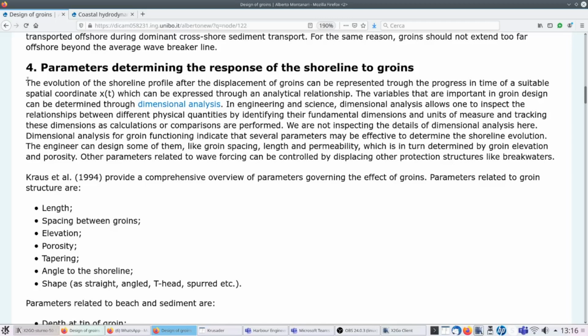Actually, what models it is the difference in along-shore sediment transport as we move along the coastline, where we have a positive difference, meaning that the sediment transport is increasing. It means that there is erosion. Where there is a negative difference, sediment transport decreasing, there is accretion.